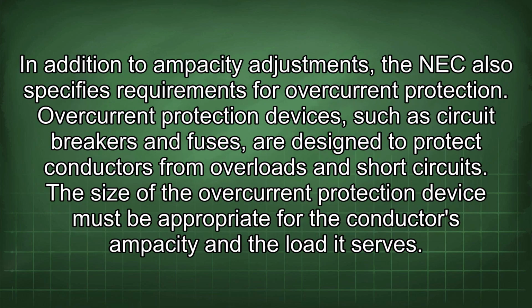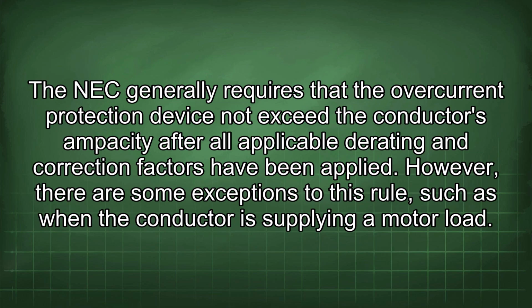In addition to ampacity adjustments, the NEC also specifies requirements for overcurrent protection. Overcurrent protection devices, such as circuit breakers and fuses, are designed to protect conductors from overloads and short circuits. The size of the overcurrent protection device must be appropriate for the conductor's ampacity and the load it serves. The NEC generally requires that the overcurrent protection device not exceed the conductor's ampacity after all applicable derating and correction